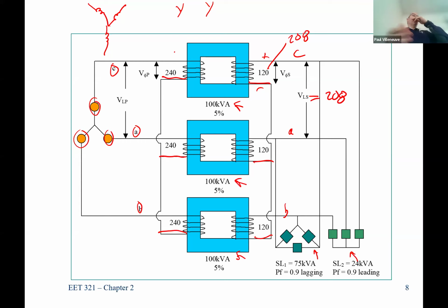So what ends up happening is the water's not coming in there at 160 degrees. Everybody would scald their hands. So it's coming in at 120. And what they do is they have these massive heating elements that heat the water up very, very quickly to 160 degrees. And they have really strong pumps and motors to drive really high pressure, so that when you take a plate out that's been sitting in whatever sauces and cheeses and all that stuff, and that stuff gets pretty sticky, it's got to come clean every time.